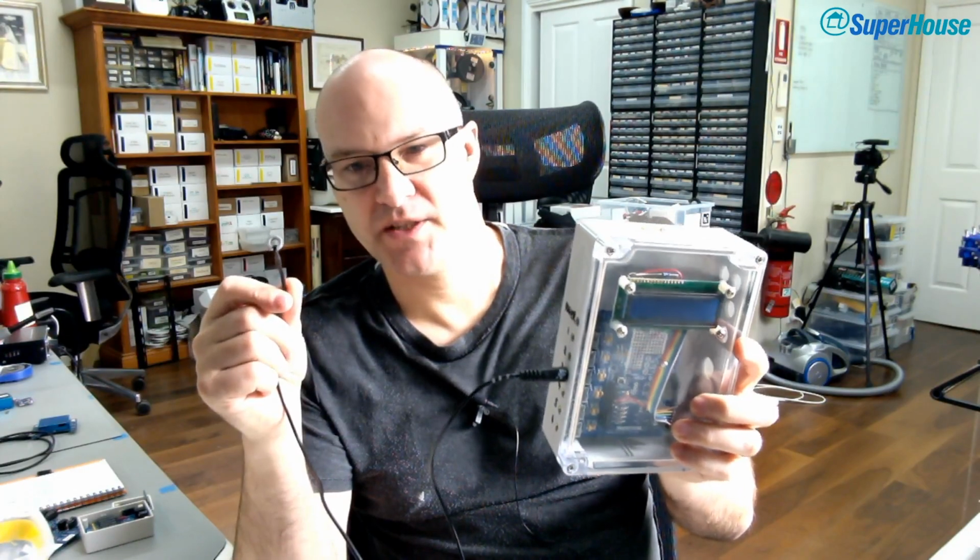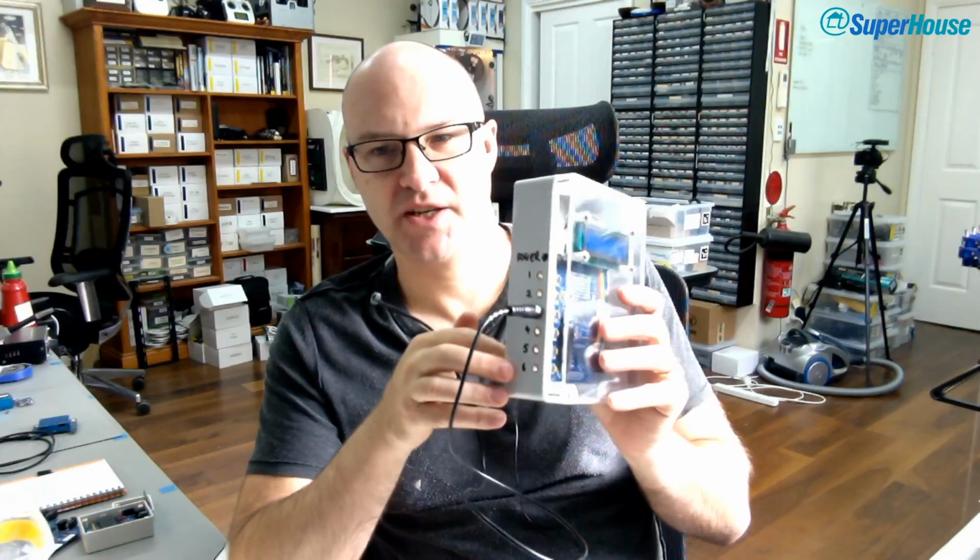With this, what you need to do is disconnect or cut the active lead to pass it through the sensor. You can't just clamp it on like that, which means this is more of a permanent installation sort of solution. This is the sort of thing that you would put inside a switchboard. You could put one of these on every power circuit, and this has got 6 input channels, and you could then read 6 individual power circuits.